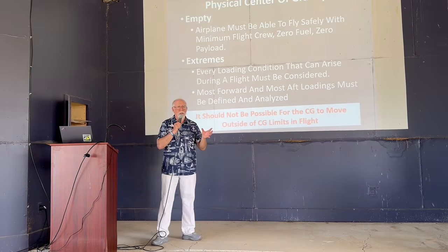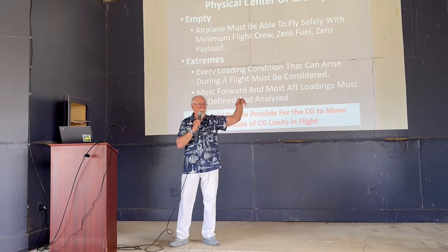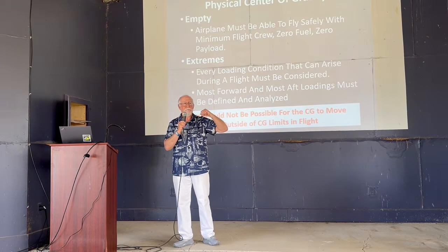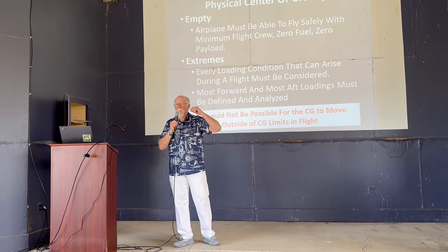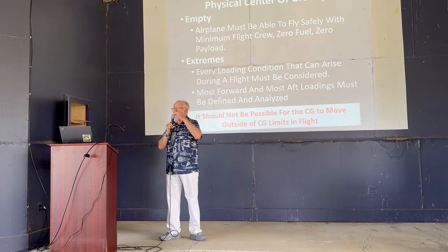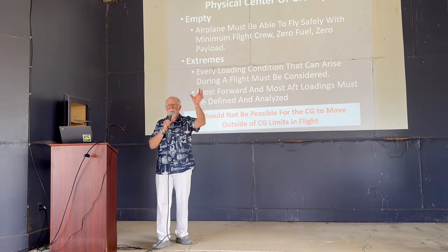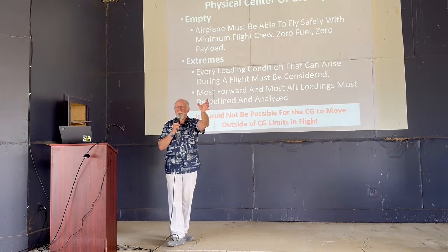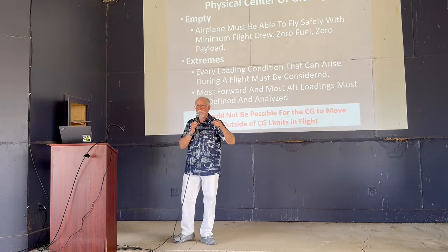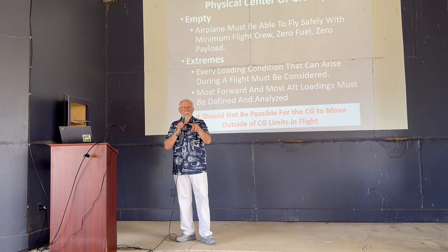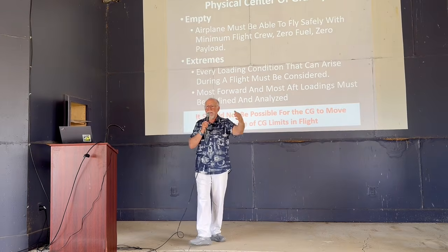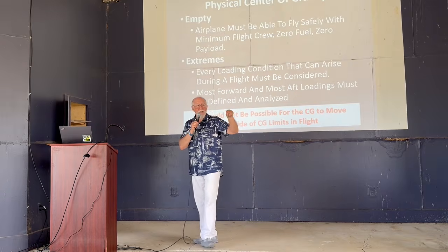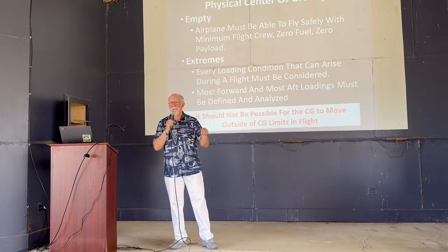On military airplanes where we drop big masses out of the airplane mid-flight, it's a big issue. But just fuel burn can do it. There was a problem on some of the early fast class airplanes where they had wing tanks and a cowl tank. The cowl tank was normally thought of as reserve fuel. But it turned out that on some of them, if you had too heavy people aboard, when you started burning the fuel out of the cowl tank, the CG would go behind the aft limit. Which means that the stuff in that cowl tank isn't really fuel. It's flammable ballast.